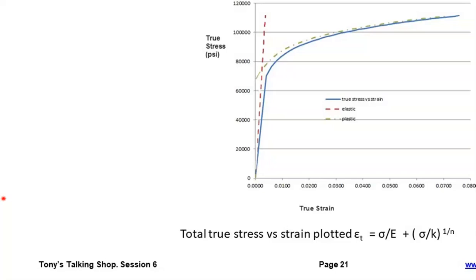So in that particular case, we're starting from a nonlinear analysis where we've got some local plasticity, and then small perturbations again on top of that. So I think that's the basis of the Seeger approach, and certainly the kind of hybrid approach that I use there, where I'm using the perturbation approach on top of the very local regions of plasticity.